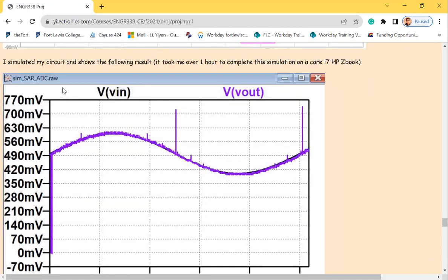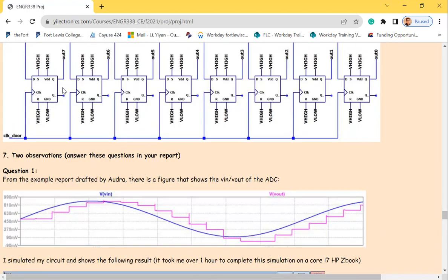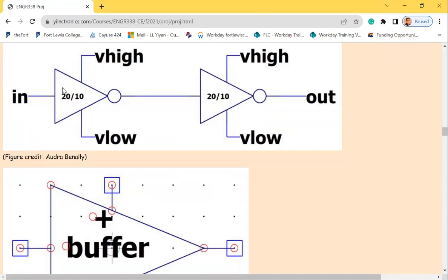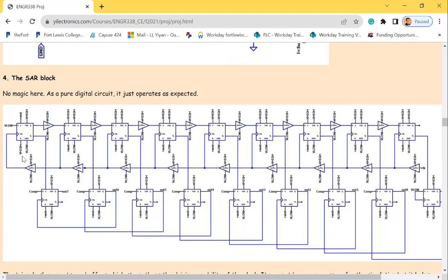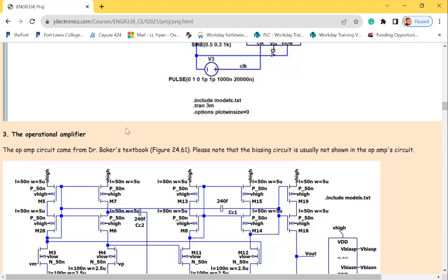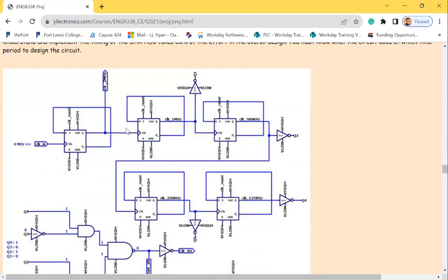So we'll go through the logic for the whole circuit later on. But now you should know why we need a D flip-flop, because if you look at the schematic on the top, these are just registers, right? See, every single one here is a D flip-flop. And I do need a set and reset in it, right? So you can pick up the TI D flip-flop like the ones I used here. It worked really well.